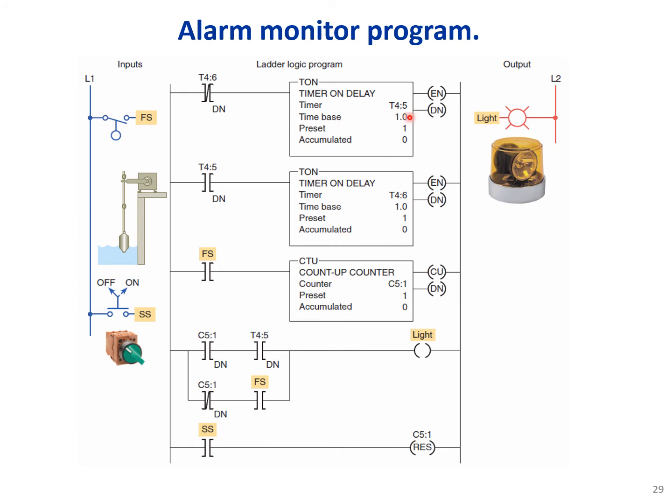We had one example before. This is an annunciator, and we are going to use it to flash this light. It goes from on to off, and here you see how we are using the downbit of them to flash this light.